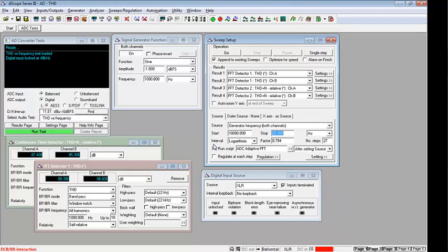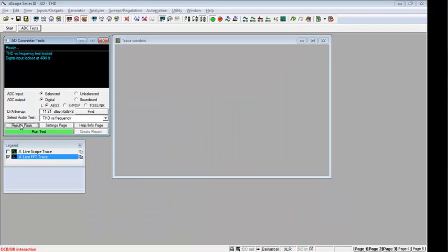And I'm basically going to measure THD and THD plus N, so total harmonic distortion, and total harmonic distortion plus noise, at each of these different frequencies. I also have a clever little adaptive FFT script here, and what this is going to do is look at both the signal amplitude and frequency and determine whether we're using a sensible FFT size. If the amplitude gets too small, or if the frequency gets too low, we may need to use a larger FFT size. Why are we using FFTs at all, you might ask?